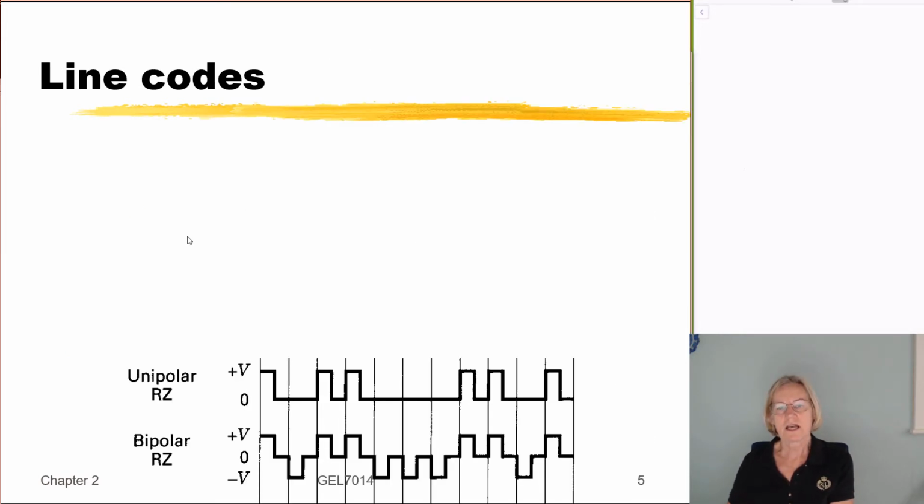Again, I wanted to point out in particular the return to 0 versus NRZ, so we can have bipolar return to 0. Normally we would have a positive and a negative voltage, and because it's a return to 0, inside of the bit time, we're stopping halfway and doing a reset to 0. Then if the next bit is supposed to be a logical 0, we'll put a negative voltage, but halfway through again, we're going to reset to 0.